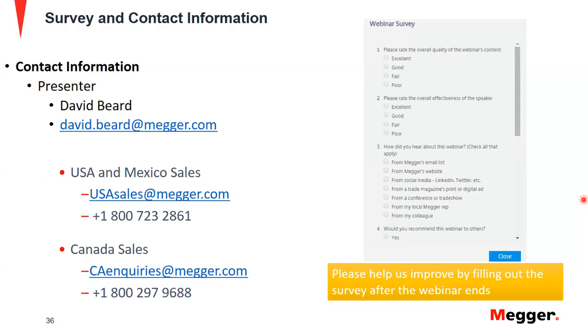All right. Sughosh, does the RTMS software allow for different frequencies, such as an aircraft, which would need 400 hertz? Absolutely. On the RTMS software, we have the option to change these frequencies independently for different channels of currents and voltages. Another nicer feature on this software is that you can generate frequencies of different levels on the same channels. One channel can generate up to 4 waveforms of different frequencies. I hope I answered the question.